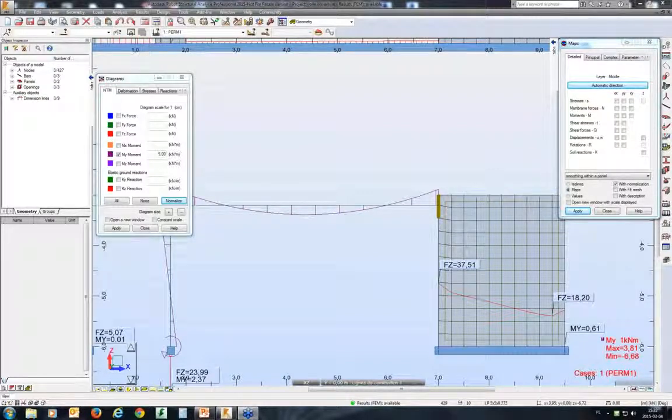Let me put it this way: unless you can predict what influence this option is going to have, do not mess with the default tolerance of the model generation. This is an option that has influence on many things. The definition of meshes is one of them, but it also influences the geometry of the model, like, for example, internally moving two neighboring nodes so that the resultant node is the middle of the original locations of these two, adjusting panel geometry.